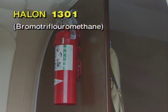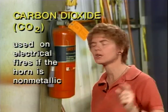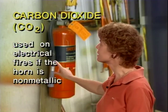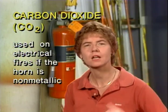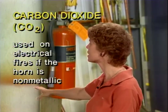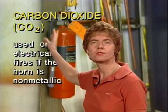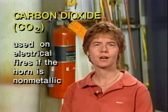Now, a CO2 or carbon dioxide handheld fire extinguisher can be used on an electrical fire, but only if the horn is non-metallic. You would not want to use one with a metallic horn if you had an electrical fire. So only if the horn on it is non-metallic can you use that CO2 handheld extinguisher on an electrical fire.